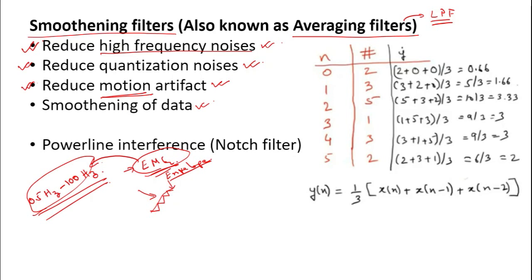I told you about this for the ECG aspect. It can be true for the EMG purpose also. So it can be true for the say needle electrodes also. In the needle electrodes, you can try to take the signal from a particular EMG muscle. So if due to some reason it moves during the acquisition process, then the motion artifact will be coming.